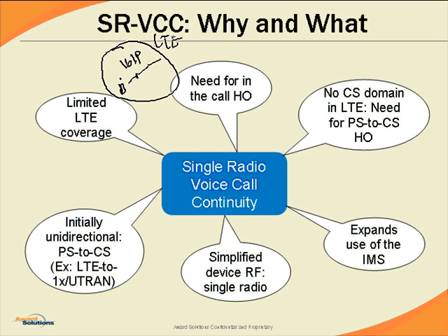And now we go outside the LTE coverage area. There is no LTE available, only CS available, legacy technology. So we have to do handover. This SRVCC is handover. We already had a voice over IP call going on, but now we leave the LTE coverage area, there is no LTE to be found. So we have to do handover, and that handover is SRVCC.